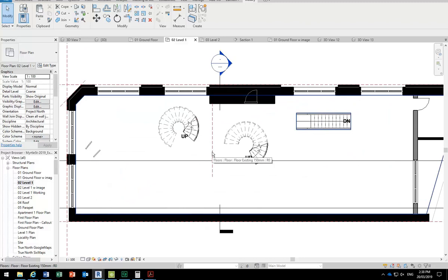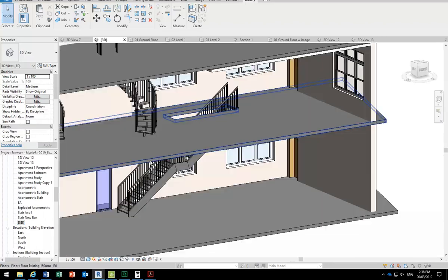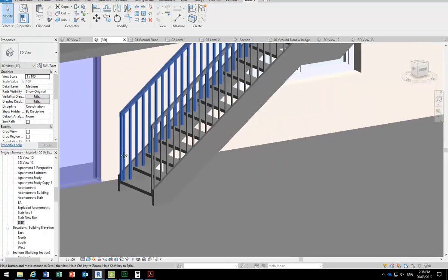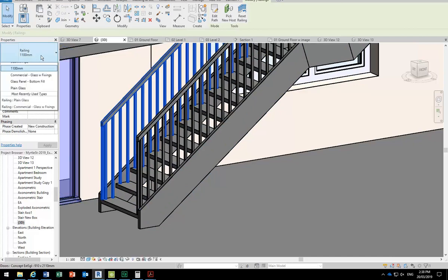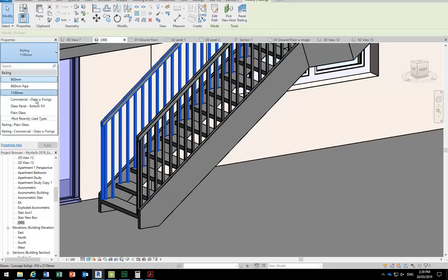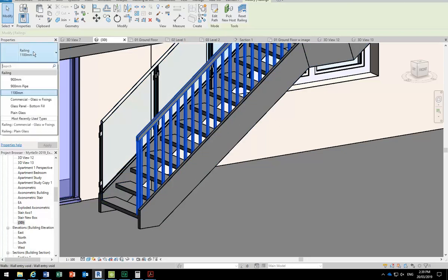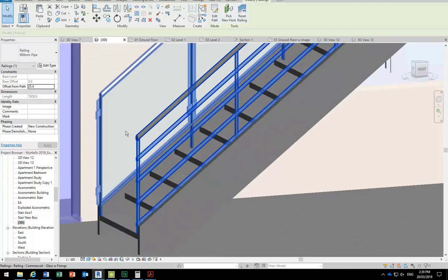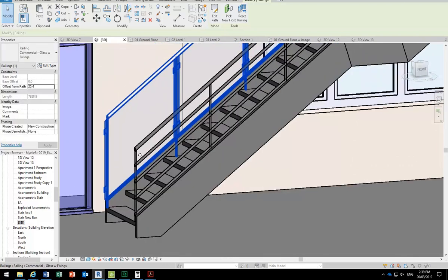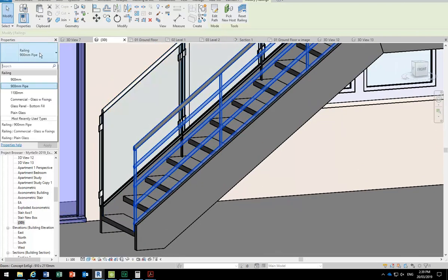It's a good chance to experiment with the stair tool, see roughly how it works, and also maybe just to finish off, have a look at the landing, so the railings that it gives you. So you can see after you make a stair, the railings come up automatically, and you can try changing those in properties, maybe just to start with using the preset ones that you're given. So we've got the glass one there and a few others that are just built in. There are hundreds in the library, but that'll get you started. And as long as you realise the railings are a separate object that's made automatically, even though there's also a railing tool.